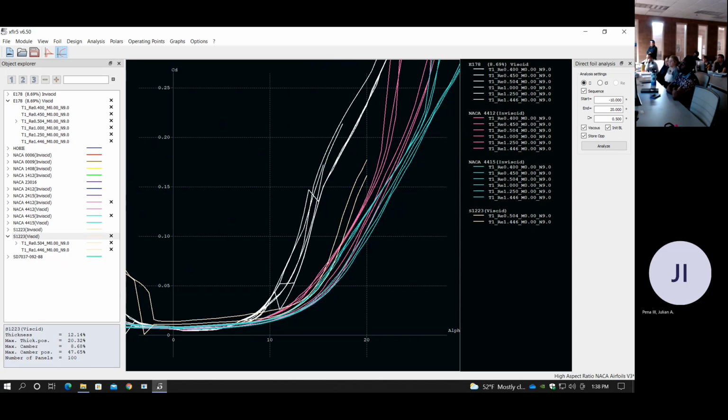However, I brought all 4 of these airfoils into the 3D plane analysis because they're the best performing ones out of the bunch. If there are any questions at this point, feel free to ask. Question: you said they have approximately the same CD. If you go across at CD equal to 0.1, you can see that the alpha value is a lot less than these ones. So you can see that it has less drag at higher angles of attack.